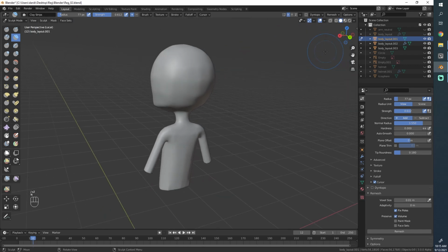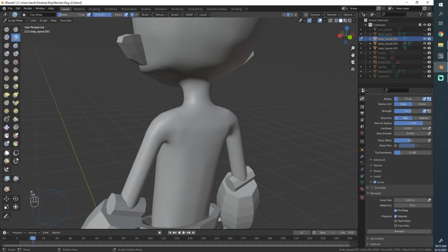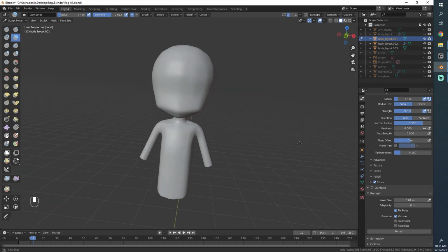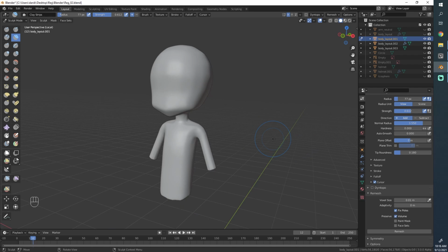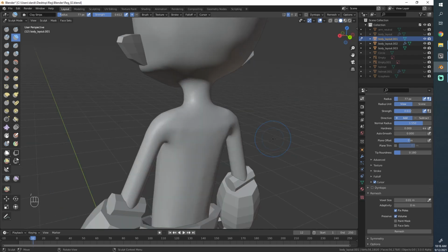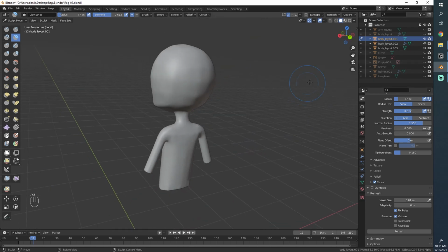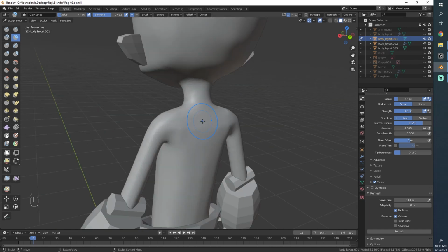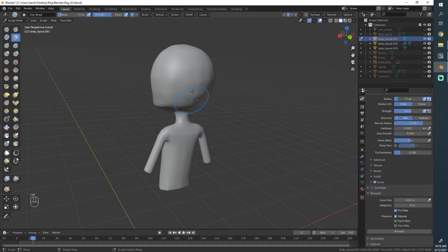No, okay, I'm not sure. But if you hit this key that you can see down here, then you can isolate the object that you're working with. Just be sure to remember to hit that button again to toggle out of that mode, because it can be quite difficult to find the reason, because if you try to unhide anything, just nothing will show. It will just seem broken until you find out that that's the button that you need to hit.